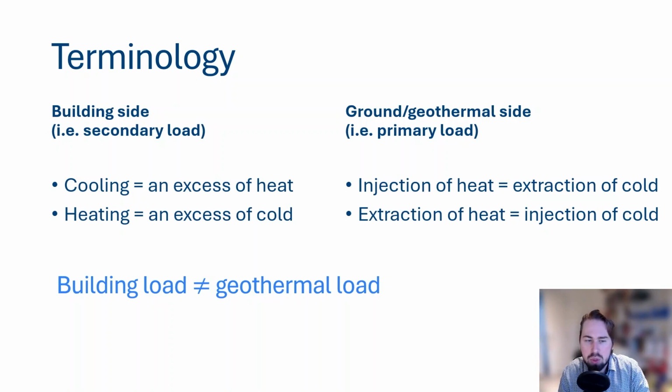And it's an important distinction because the building load is not the same as the geothermal load, because there is a heat pump in between. So your building load in heating will always be higher than your geothermal loads, because the heat pump with its own electricity consumption will take part of the heating load for itself. So in order to make sure that you do not oversize your Borefield, it's important that we know that there is a distinction between heating and cooling and injection and extraction. So in this series we will be mostly talking about injection and extraction to make the distinction as clear as possible, but just be aware of the difference.